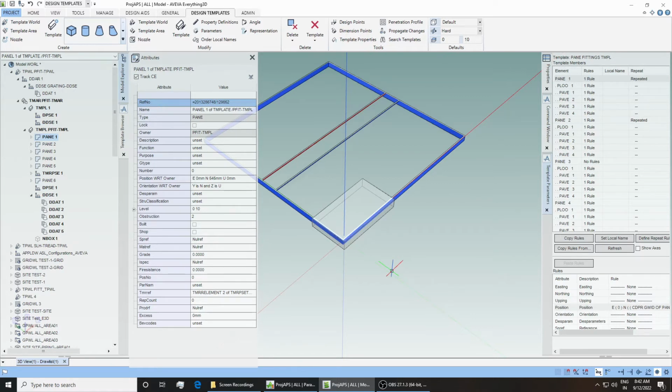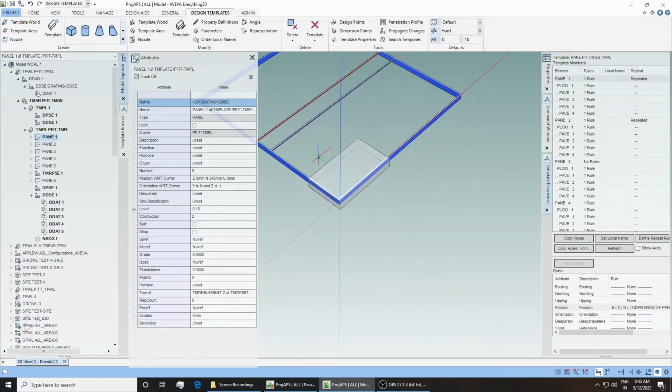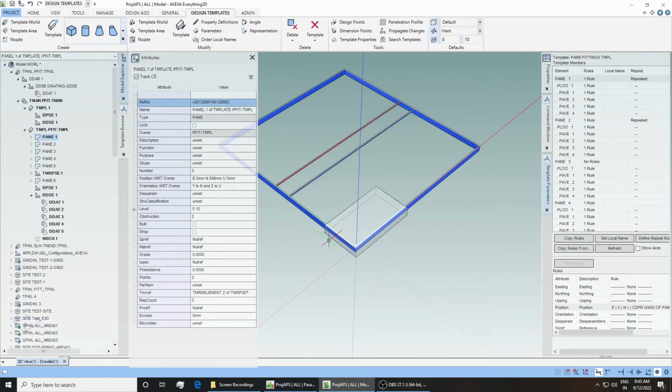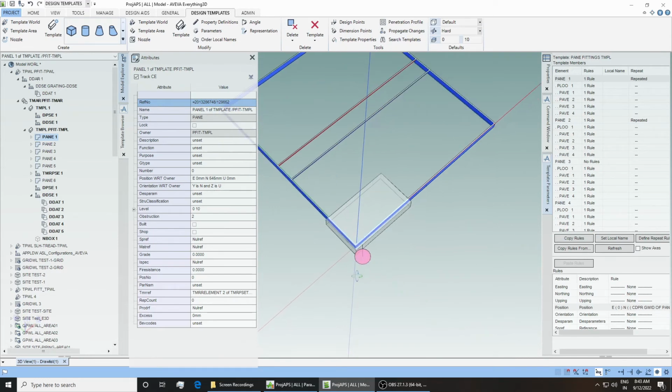in the case of a template, this 000 world point, this 000 with respect to world, is the reference point. If you create a template far away and you want to use that template while creating another detailed specification or fitting something like that, in that case also the template will be created far away with respect to that owner. So you have to keep in mind that you have to create this template with respect to 000 in the world axis. Okay, so here in my case, this is the 000 point.